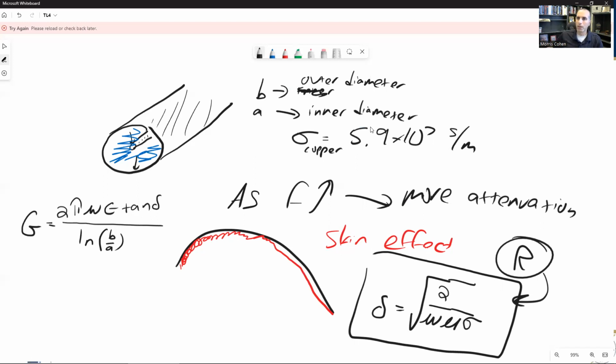All right, so that concludes this video and this section on transmission lines with AC signals. I hope you can now see that the analysis techniques are very different depending on whether you're talking about digital signals with square waves, rapid falls and rapid rises, or whether we're talking about RF or analog or sinusoidal signals in which we're operating in a narrow frequency band. That narrow frequency band introduced a whole host of conditions that weren't the case for time domain signals.